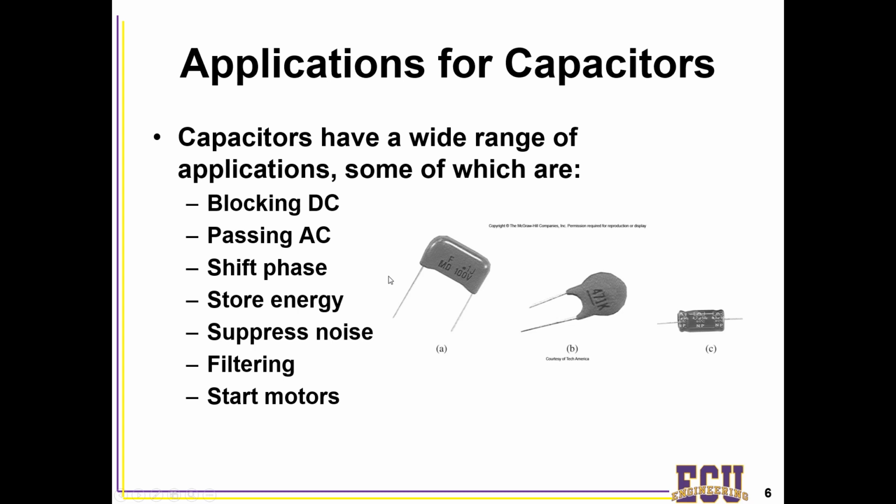Why is it doing that? Well, the battery itself, typically a AA or AAA battery in a camera, doesn't have enough current sourcing capability to be able to use the flash module with it. And so what happens is you actually store the energy in a capacitor, and then the capacitor can discharge that charge very quickly through the flash module, much faster than the battery is capable of doing.